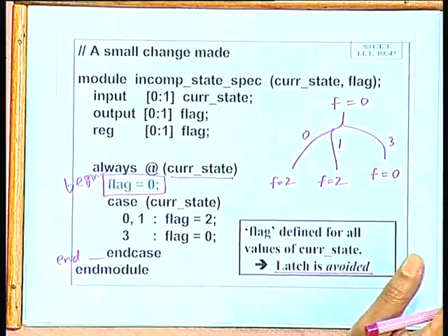But sir, for the simulator, how does it make a difference whether the variable name is the current state or the variable name is clock? For the simulator it does not matter, but for the synthesizer it matters. You can map it or synthesize it as a flip flop or as a latch, and a latch will be enabled continuously. But if you simulate, the value will be the same in both cases. Maybe if you have a latch, the delay will be slightly more.